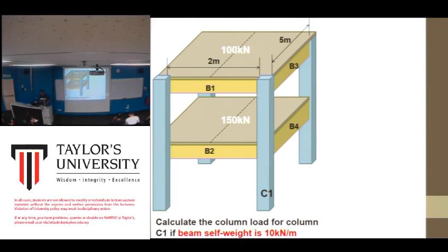I know that in the previous topic on beams, you learned about the ultimate load, but you don't have to consider that. You don't have to multiply with the 1.4, 1.6. Just use any information that you have from this image to derive the total load.